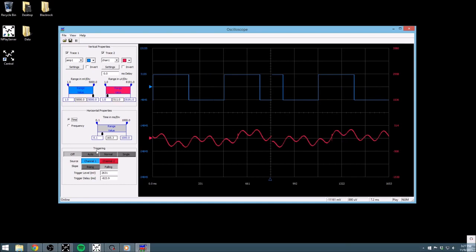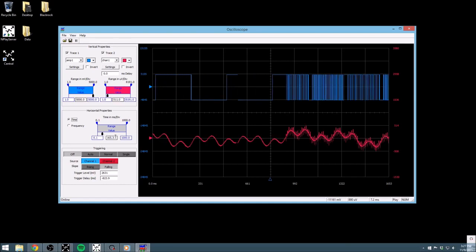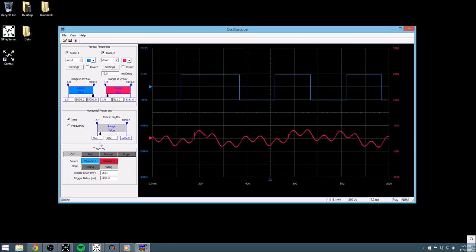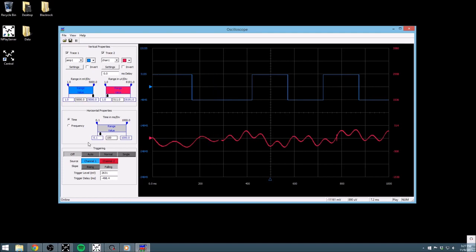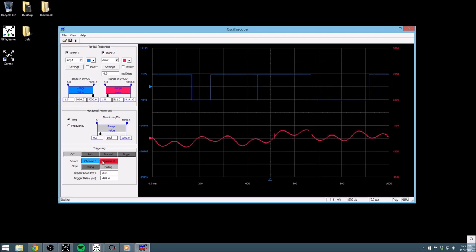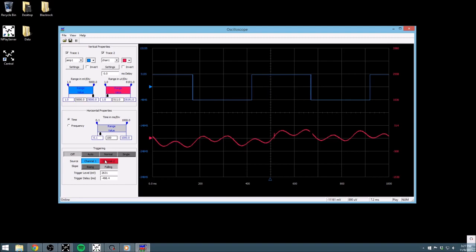I have a repeating square wave on my analog input 1, that could, for example, represent a sync pulse coming from my stimulator. I'm going to set my milliseconds per grid line to be 100, so it'll be easier to see triggering in action. Additionally, I would like to trigger off channel 2, which I have set to be my repeating analog input. I care about what happens immediately following stimulation, so I'll use only the falling edge of the signal.